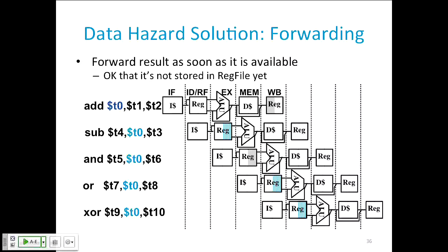So one really cool trick you can do is called register forwarding, or sometimes register bypassing. And the trick here is, I haven't written it to the register file yet, but I do know the value I'm going to write to the register file when I get there, and it's sitting inside the machine at a point that I can steal it and sneak it into the next instruction.